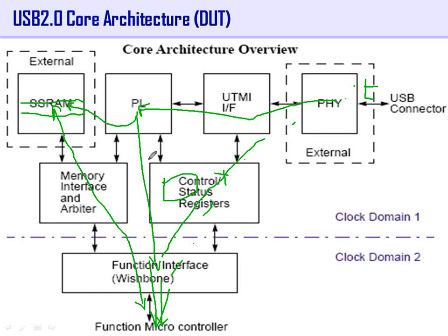Who decides all this information? My host will decide. The host has a device driver, which is getting requests from where? Application level. Through that application level, it knows what is the priority of each application request. Is it for the music player? Is it for the pen drive? Is it for the printer? Is it for the keyboard? Accordingly, it knows. For the keyboard, you don't need to get a request from up, right? It already has a counter, some kind of counter generated now. Next, I will generate after 50 frames. Next 50 frames, like that. Accordingly, keeping all that information, it keeps generating frames or microframes.